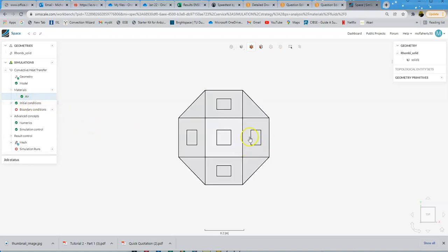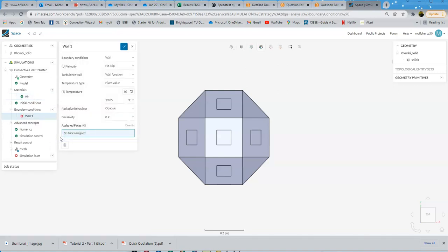And we also need to set the rate at which heat is flowing in at the bulb on the inside. So when we do that, we just specify that as 100 watts, or a certain amount of watts per meter squared as well. So we're ready to go on to the boundary conditions. So we'll see what's given there. Each of ours is going to be a wall because they're all solid. And we're assuming that there's no loss of fluid or loss of air in or out, that it's perfectly sealed. Mightn't necessarily be the case, but it's close enough.